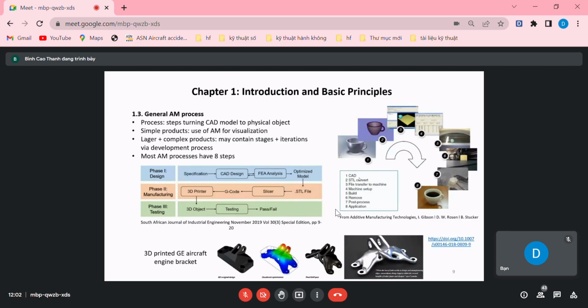This is necessary to guarantee that the CAD model is waterproof. In other words, there is no hole on the surface of the STL model. If any defects are detected by the software, then you need to repair and modify the model so that the waterproof property is maintained.